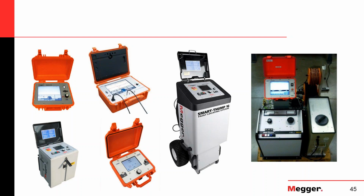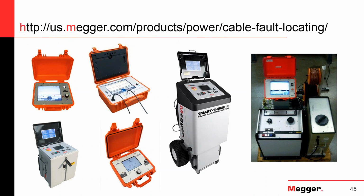probably more convenient for downtown network fault location. This is an SWG 3500, so you have a surge generator and additional capacitor to provide you more energy. On the right, you can see the filter that was talked about for arc stabilization, and on top you can see the radar. This is a typical van-mounted system with very, very high energies that you need in those downtown networks or for PILC cables. And if you want to know more about the product line, this link will help you.